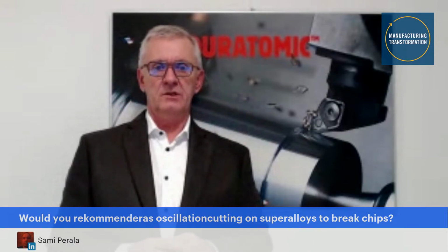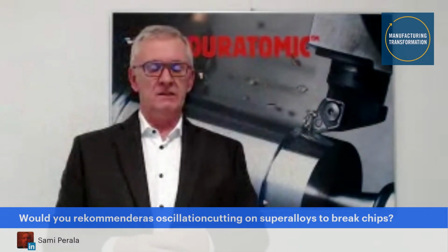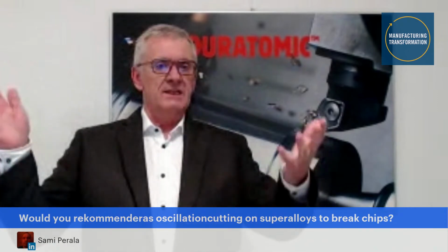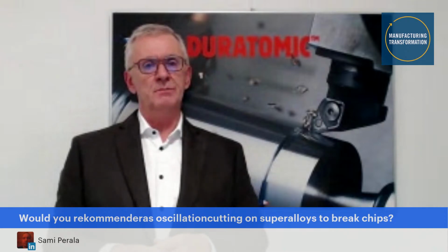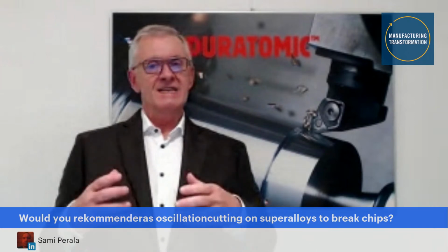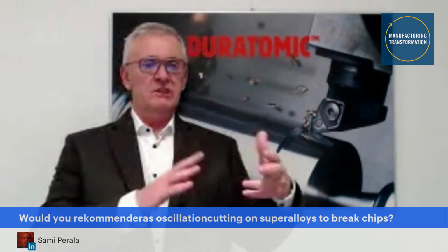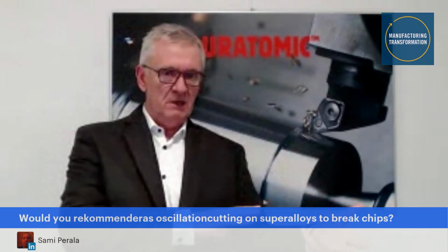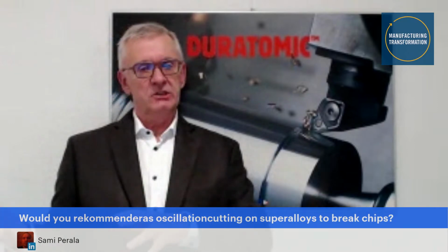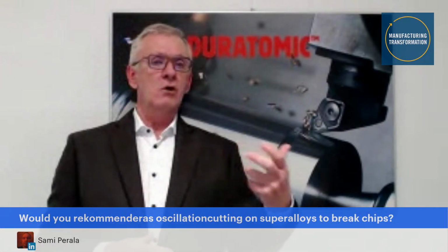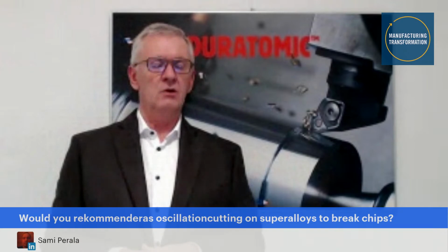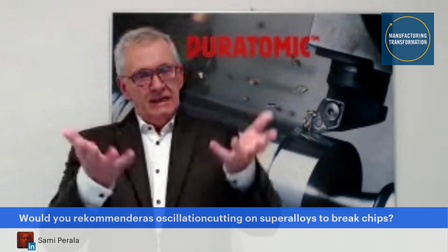I have to be careful a little bit here. But in most other materials, longer chips are more fluently formed. How do you create a longer chip? By reducing the feed. And in doing so, you see that you will have less micro vibrations, less segmentation, less chipping on cutting edges, longer tool life, and so on. But lower feeds jeopardize the productivity of the operation, the efficiency of the operation, or effectiveness, sorry. And here we have a dilemma.